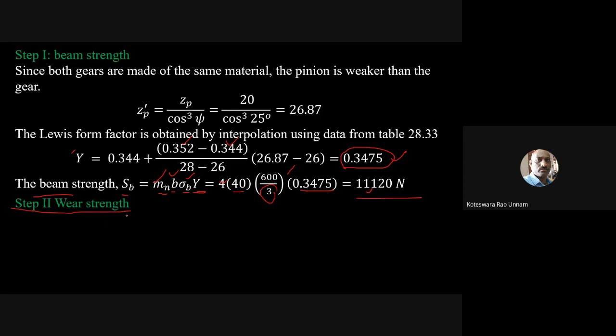Similarly, you can calculate the wear strength also. So why are we calculating beam strength and wear strength? We need to check which one is the lowest one. Based on that only, you can calculate the rated power.